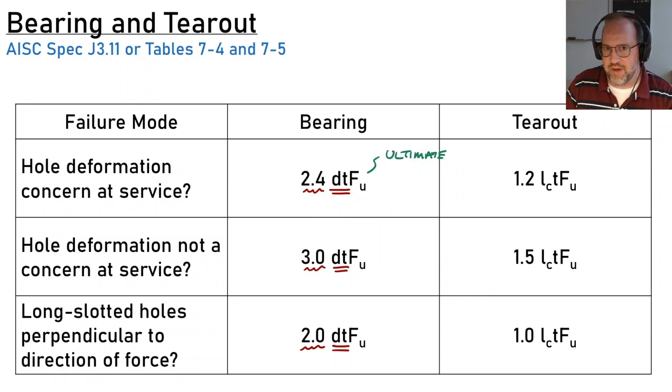The last case is special. If you have this, you have to use it. So that's long slotted holes perpendicular to the direction of force. We don't really care if deformation is a concern. If you're doing something like that, you get a reduced capacity.